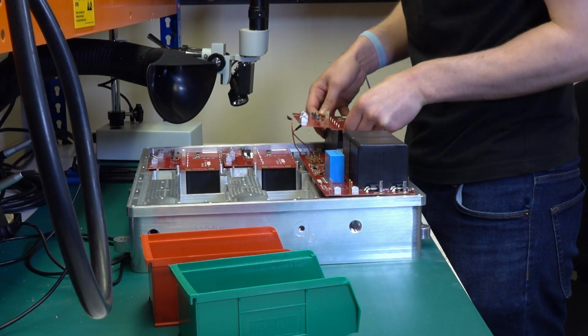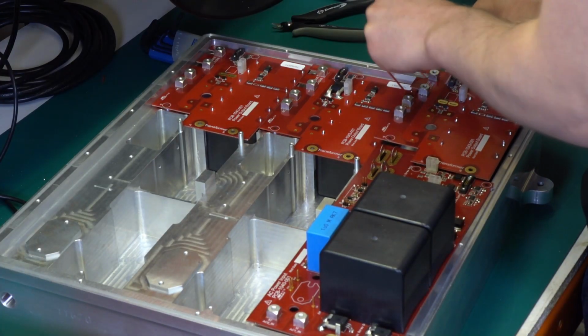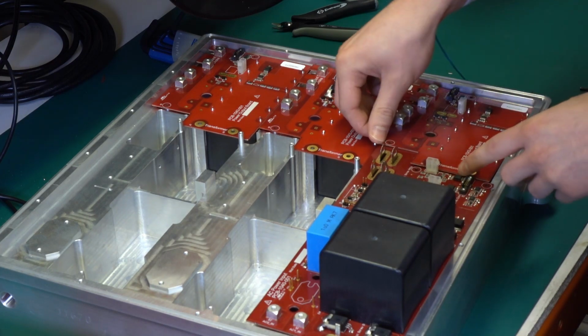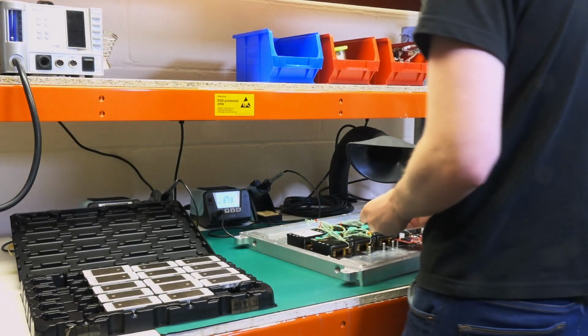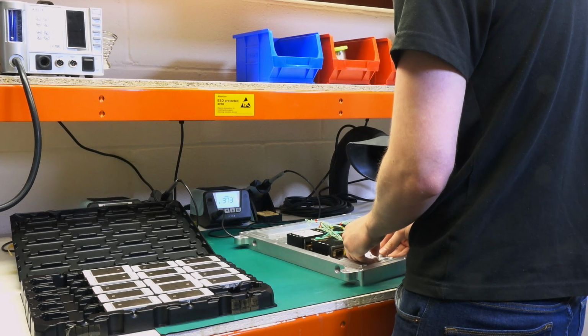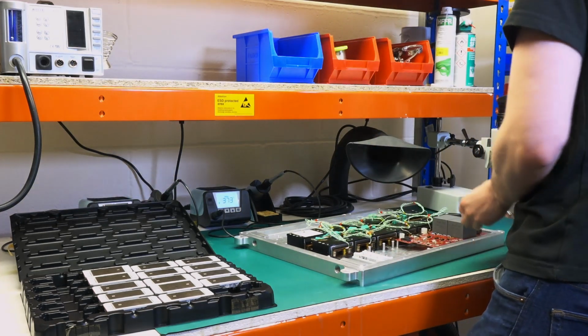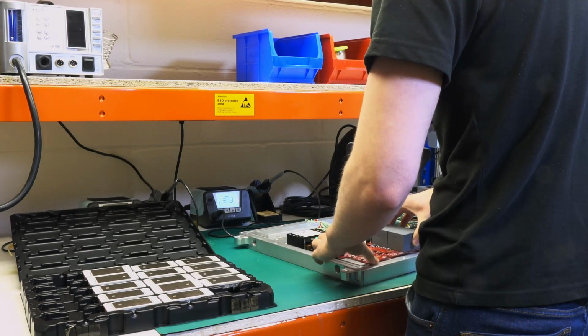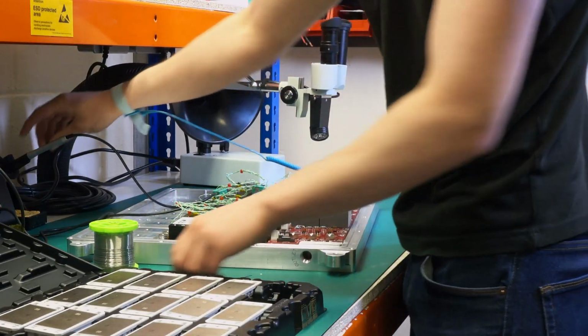What we are focusing on within AVID is the use of silicon carbide devices, which are still fairly new to the market. The supply chain is catching up rapidly, and the suppliers of those components are putting a lot of effort into getting those devices into maturity, and also bringing online automotive standard devices and modules to support that. The benefit that they offer is that we can switch at a much faster rate, so we have reduced switching losses in those devices, much more efficient, but also that we can switch them at a higher frequency as well because of those reduced losses.